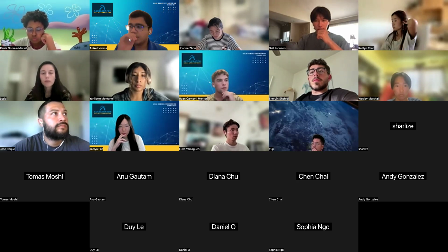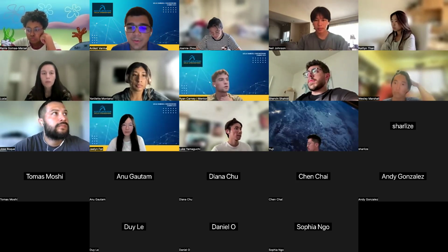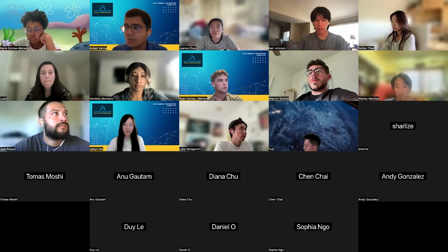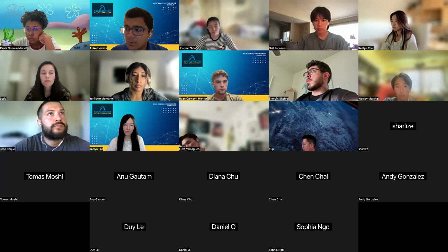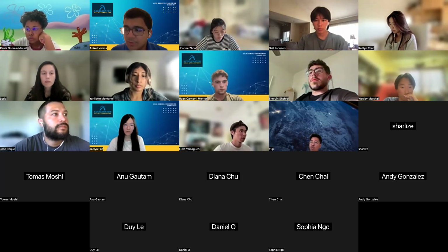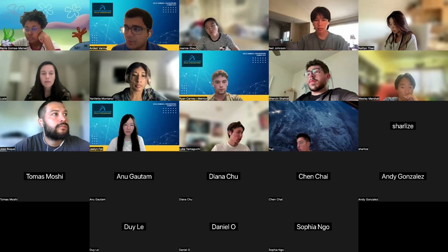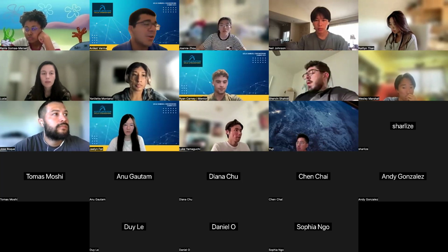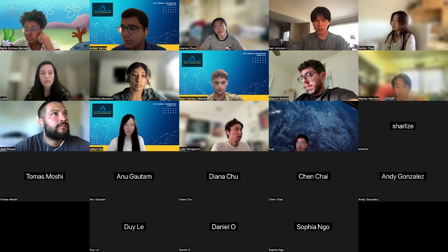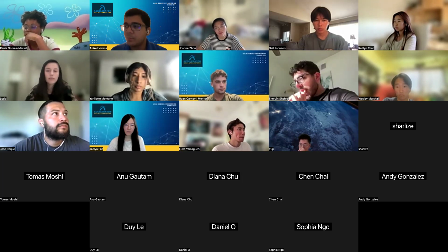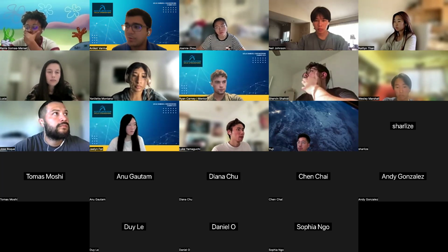A couple of reminders from last time. This might help jog your memory, but basically we covered sketching. We covered how to make a new sketch, how to use the dimension tool to dimension your sketch, and the various tools we have to create different geometries. So we had a circle, arc, square, rectangle. Then we had a dimension tool to dimension each one of those things individually. One rule of thumb was make sure that there's no blue lines in your sketch. Whenever you have a blue line, you know that particular object is not defined.